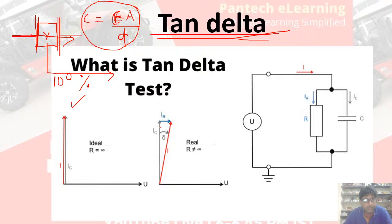The resistive component is in phase with the applied voltage, but the capacitive current leads by 90 degrees. If you take the resultant, it is the red color, and this angle is called delta. This delta gives the healthiness or the aging of the insulation system. That is why this test is performed, to predict the insulation level of the machine.